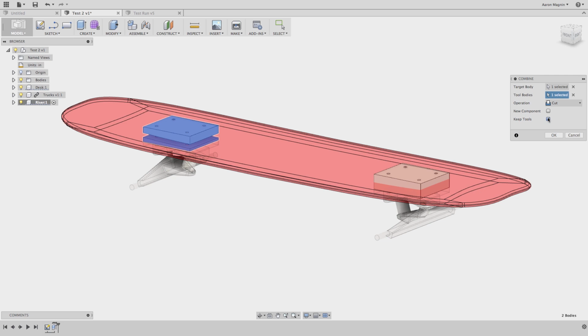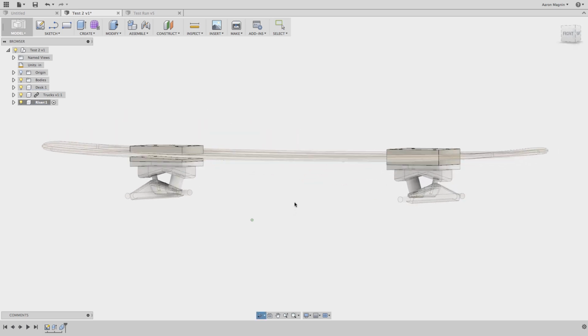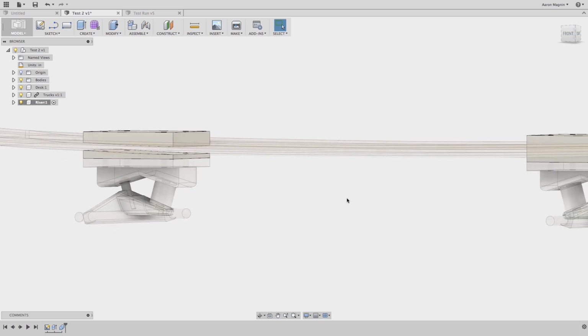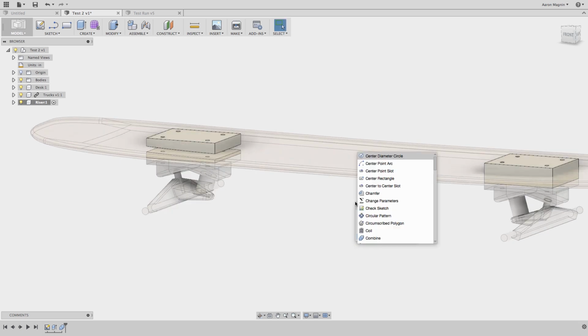I'm actually using the deck itself here to make a cut, but I don't want it to go away, as you might guess. I'll click OK, and that's going to ensure that that riser fits to that deck, no matter how the shape might change, no matter how I might go back to the T-splines and refine the shape that we have at that point.